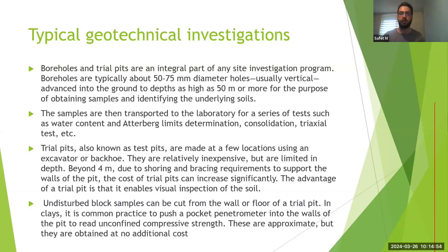For tunnels it's a bit less, but generally speaking, the deepest one I saw in my life was in Frankfurt for one skyscraper that was 200 meters tall. We had around 80 meters of depth of the borehole. What you want is for your borehole to reach bedrock. Bedrock is basically like the mother rock, the safest piece to build on, and you generally want to reach it.